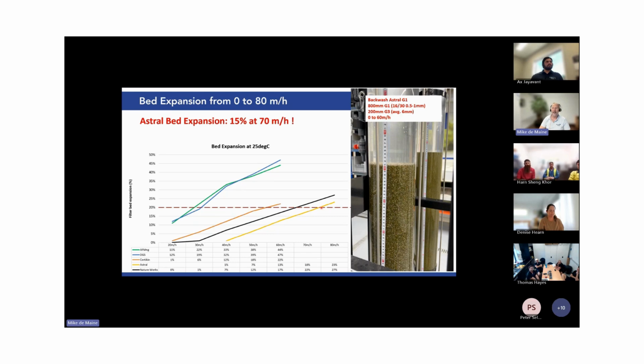So two things: if you look at our documentation, we always recommend 40 meters per hour backwash velocity. Why is that? If we get bed expansion at 28 meters per hour, it's because in most applications, your organics, once they combine in your filter, become heavier than what 28 meters per hour can deal with to lift those organics out of the filter. So what ends up happening if you're not backwashing at 40 meters per hour, you might be getting fluidization and bed expansion, but your organics are too heavy to be lifted out of the filter, so they end up sitting on top of your filter bed.